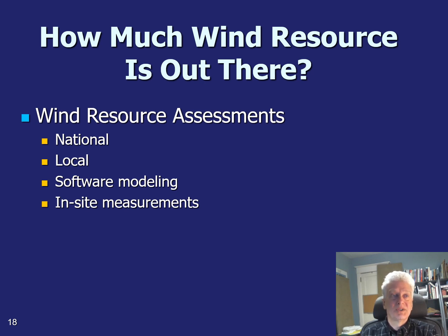So you can do what's known as a wind resource assessment. This is something you can do on a national scale, maybe even just on a regional and local scale. You can approach this by aggregating lots and lots of existing wind measurements, but typically you do it with atmospheric airflow models. So you use software, and when you come to an individual site, then you can look at putting in instruments dedicated specifically for the purpose of getting really accurate statistics about how often the wind is blowing, how strong it is. And generally that'll be a 1 to 2 year study.